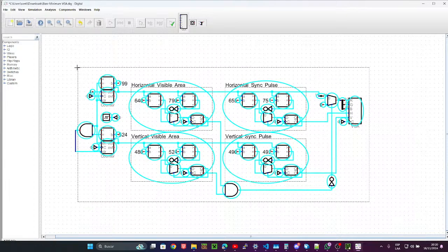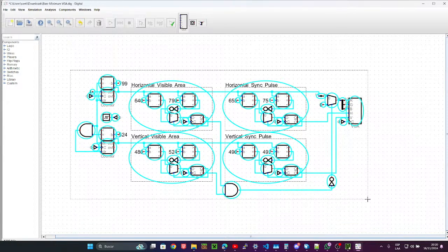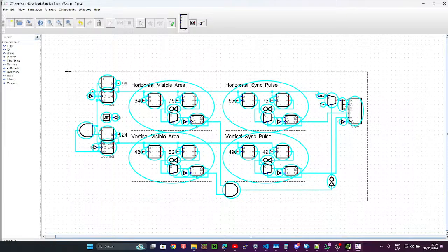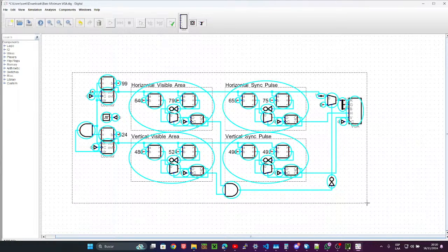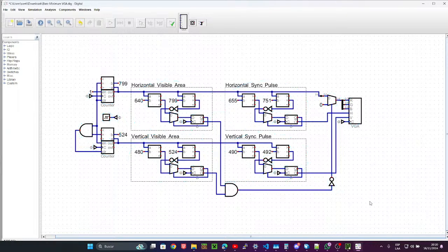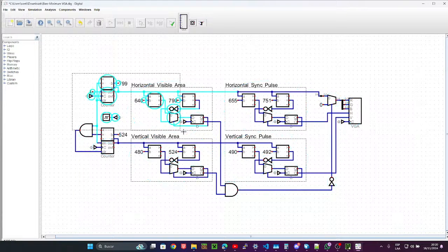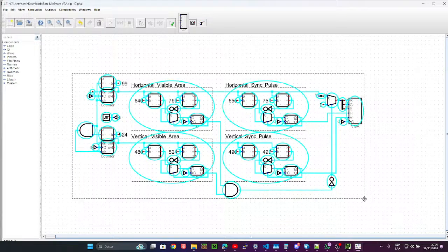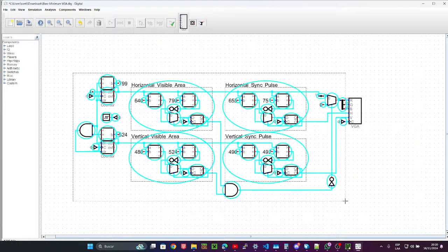That's called tile mapping. So you go from 307 kilobytes for primary memory to 80 by 60, say 16 bits to describe each entry. You drop to 38, no, kilobytes, no, is that a bit too much? 80 by 60 times 2, 9.6 kilobytes.